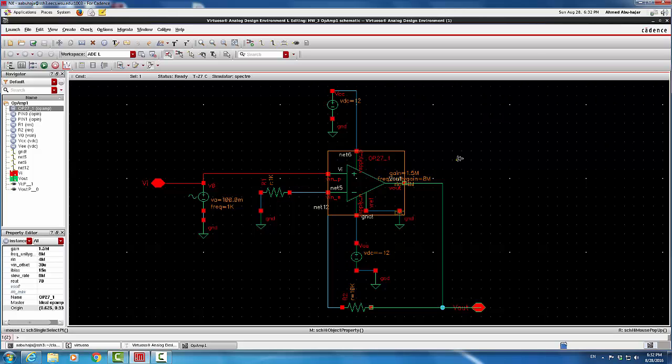This is called a behavioral model of the op-amp. We entered the parameters that describe the behavior of the op-amp. We got those parameters from the data sheet. We were able to build a non-inverting amplifier. We ran transient response, and we looked at the gain at 1000 Hertz when we applied an input signal, which was a sine wave.